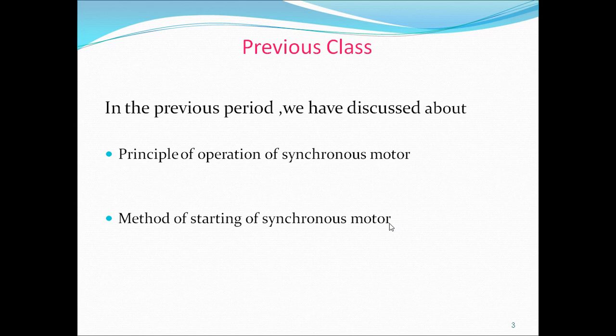Similarly, when we give the excitation, the rotor also produces poles, north pole and south pole. But in the first half cycle, the poles are the same, that is, the north pole of the stator and the north pole of the rotor are in the same direction. As we know, like poles repel each other. Due to this phenomenon, the rotor tries to rotate in the clockwise direction.